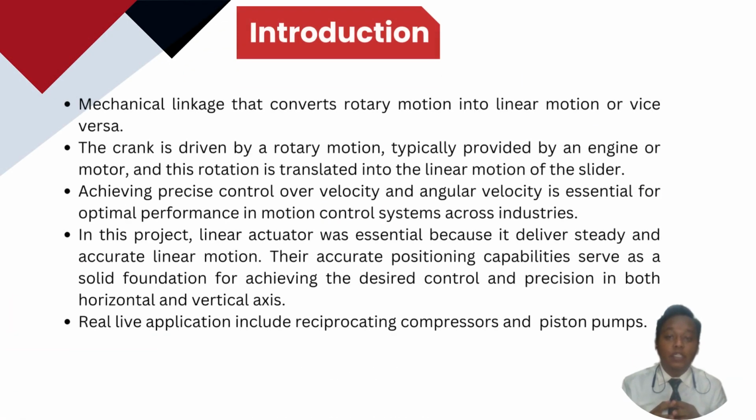The slider crank is a mechanical linkage that converts a rotary motion into a linear motion or vice versa. The crank is driven by a rotary motion, typically provided by an engine or a motor. For this project, we use an actuator, and this rotation is translated into a linear motion of the slider.